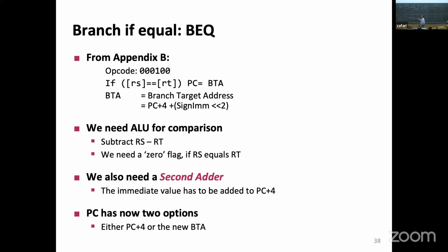And what happens in this control path is actually quite simple. You take a look at the opcode. The moment you look at the opcode 101101, you know what you should be assigning to each one of these control signals in the same cycle. So the moment the instruction is available, you know what this is. You also already directly know how you should be controlling each and every individual control signal to configure the data path to do what you want. Sorry, yes.